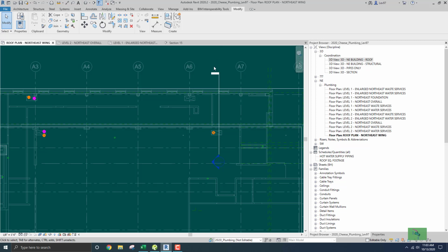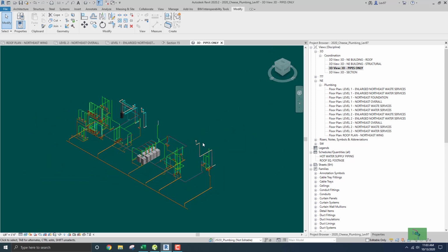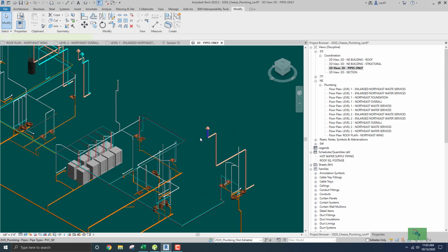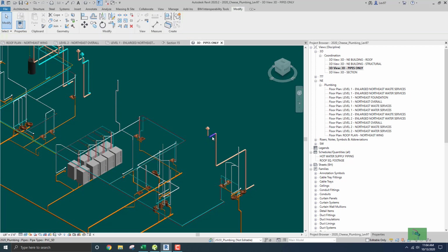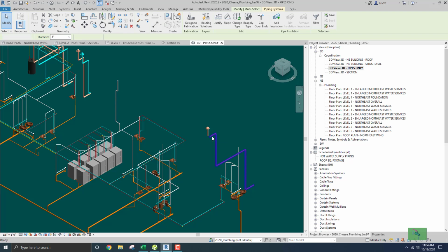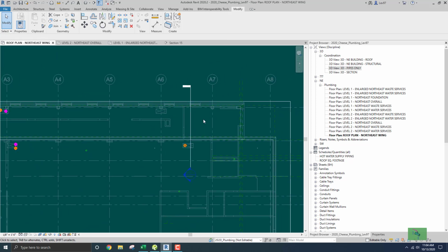I think I'm gonna go here, because I know what that is. And just erase all of this. Erase, no, let's keep that part. Erase this guy. What's Revit doing? Highlight tab so that all of it is highlighted. I'm hitting the delete button and going back to my roof plan. But I know that I'm going to need to go to the right and go down in this area.